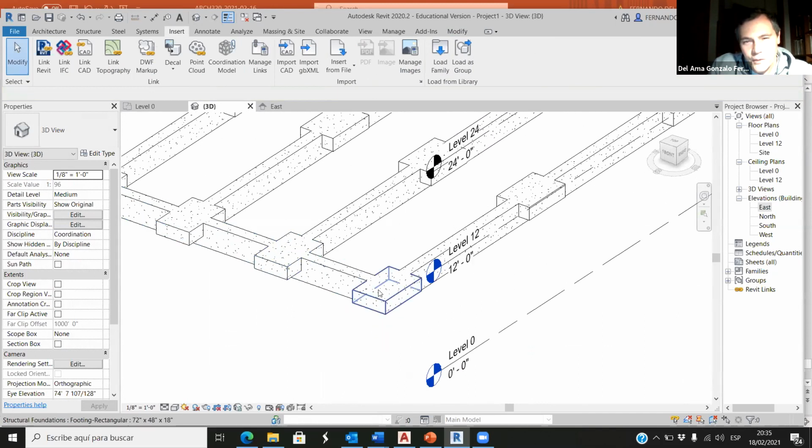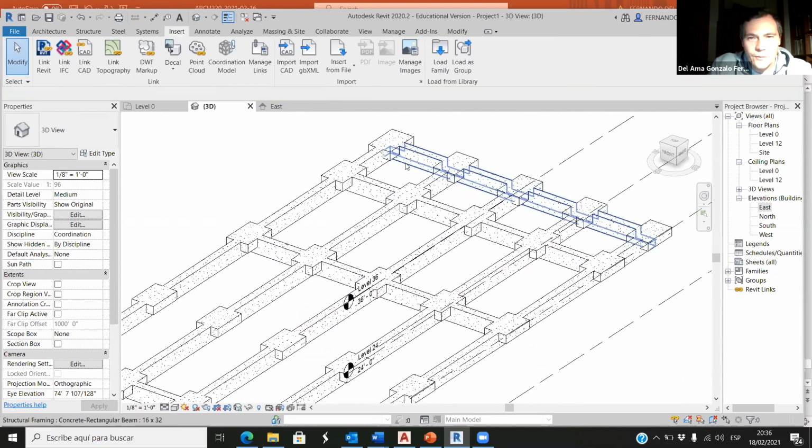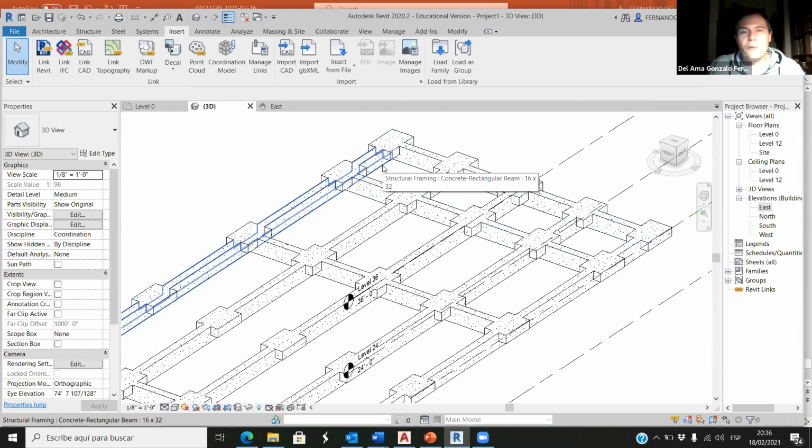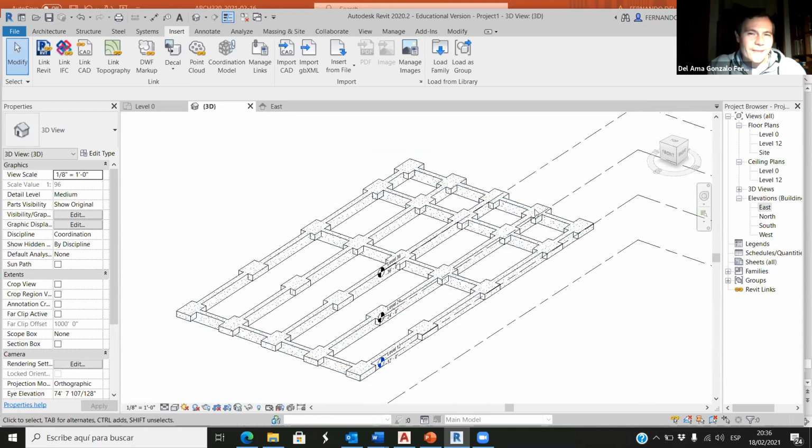If we connect this footing to this footing with this beam, because with soil we don't know anything about it. We can have some testing, but we don't know. Maybe there's a hole here, or something weak. We have rock, but at this specific point there's a hollow or space. That happens in Europe; every time you dig something, you start finding skeletons and dead people. I don't think it's that way in the United States, but you don't know what the soil is. So if you connect all of them, if there's something weak in this part, at least they are all connected, and the whole thing will work almost as a slab.